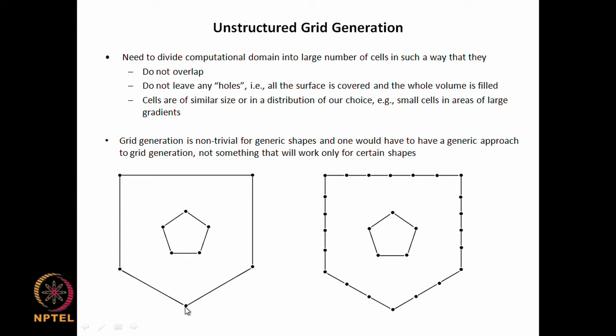You would like this velocity variation to be resolved. So you would like to have a few grid points, maybe 3-4 grid points here, so that the velocity at this point is here, at this point is here, at this point is here, and when you join them you get this straight line. So the steeper the gradient is, the smaller the grid spacing will be. The more regular the variation is, the fewer the number of grid points.